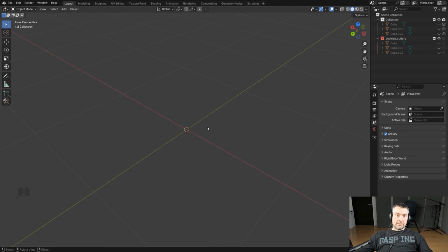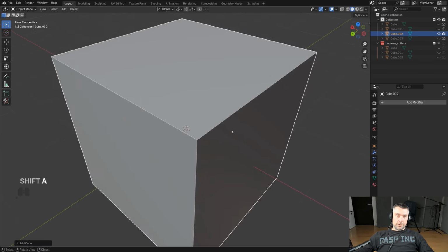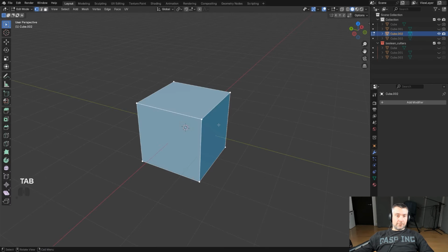And we talked about Z-fighting, so when two surfaces are overlapping one another, you know about that. So all these could cause shading problems, so you need to always check for double faces, double verts, floating verts, loose geometry. And remember also that when you're going to duplicate something from a mesh in edit mode, it doesn't really create a new mesh.